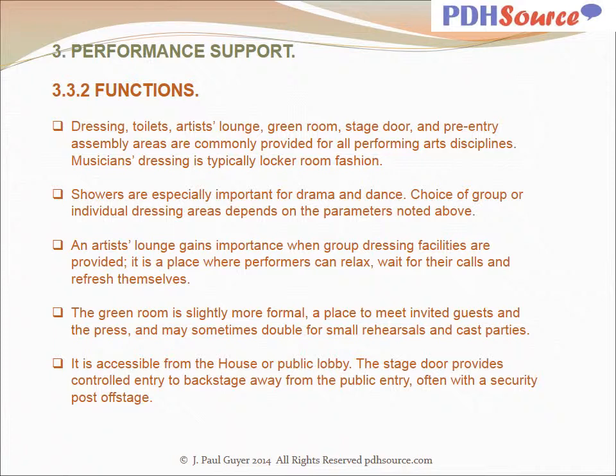Dressing, toilets, artist's lounge, green room, stage door, and pre-entry assembly areas are commonly provided for all performing arts disciplines. Musicians' dressing is typically locker room fashion. Showers are especially important for drama and dance. Choice of group or individual dressing areas depends on the parameters noted above. An artist's lounge gains importance when group dressing facilities are provided. It is a place where performers can relax, wait for their calls, and refresh themselves.